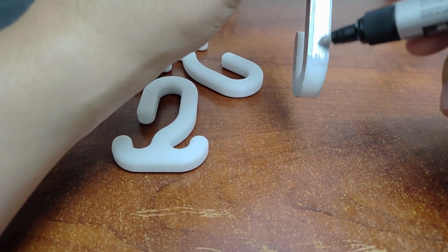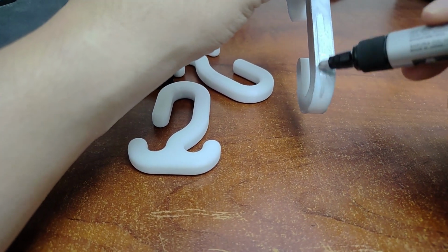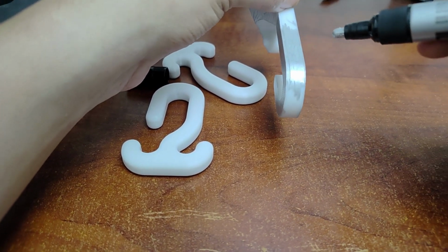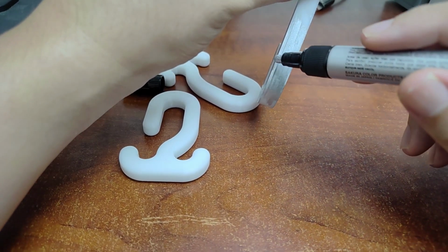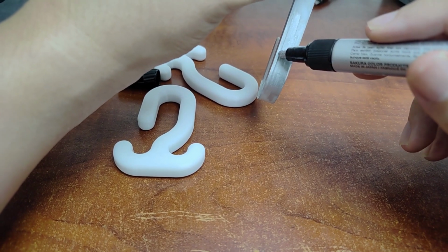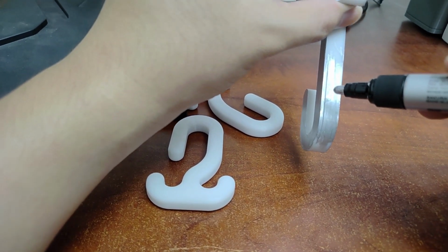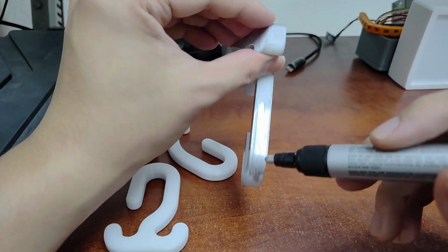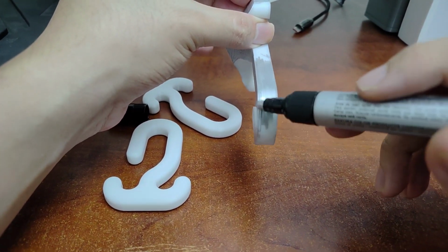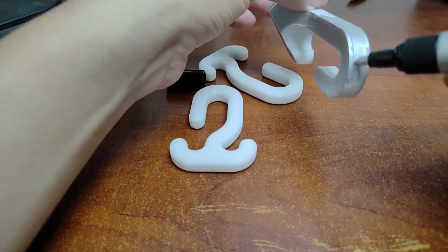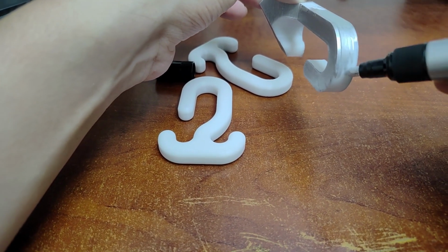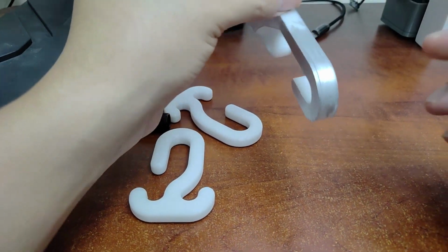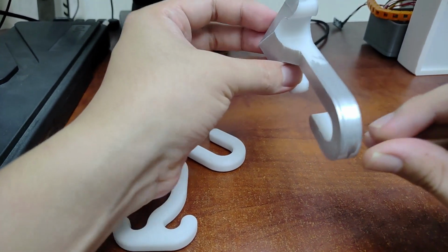The one thing that I like and dislike about white filament is the fact that it can hide the defect. This is not a layer shift, but something like a shrinkage. Yeah, layer shrinkage, because some layers took a lot of time to cool off. It can leave uneven cooling between the layers, and that will show on the final product.